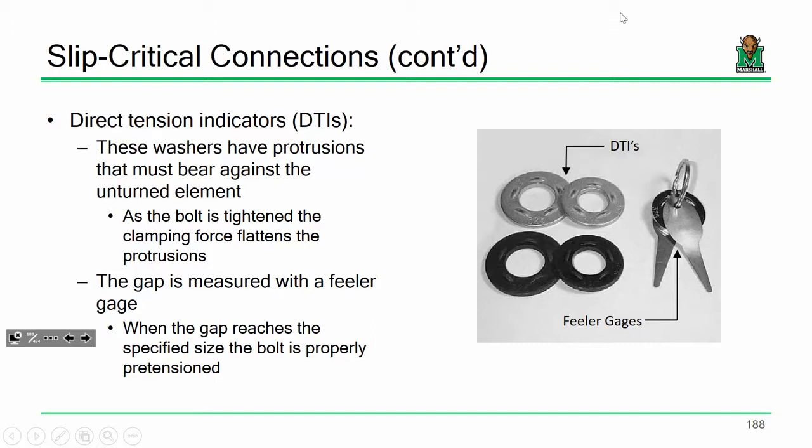But the inconsistencies actually work more in our favor than they do against us. Okay? More often than not, what you find in the field is the amount of torque that we rely on versus the amount of torque we actually get. We actually get a whole lot more. So much more that the amount of torque that we rely on, we actually bump it up 13%, because statistically, that's how people tend to wrench on bolts like crazy. I guess it's just sort of common practice. Sound good?